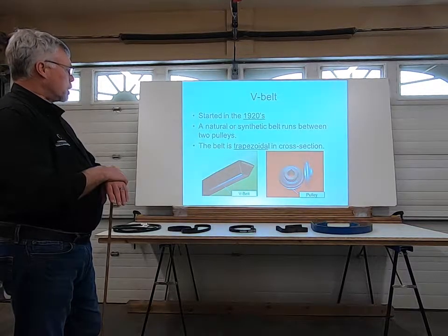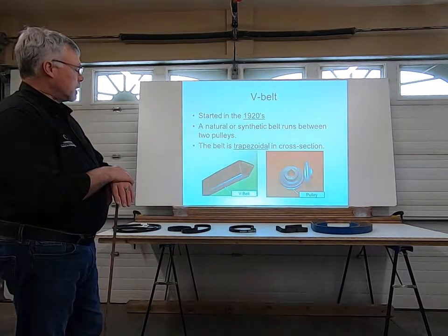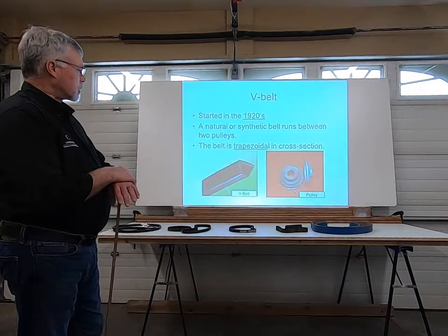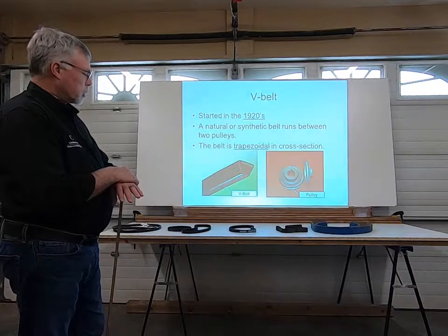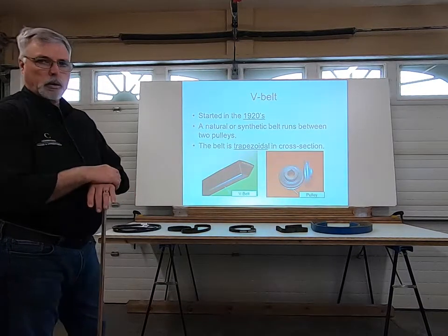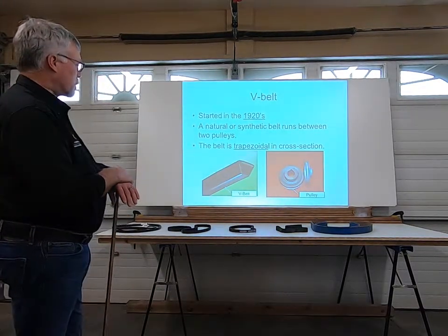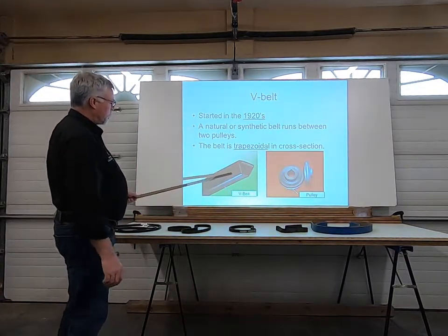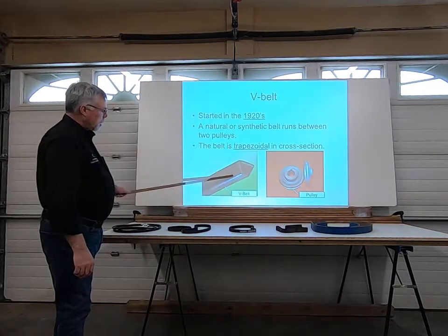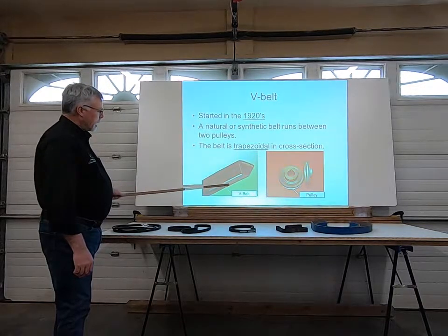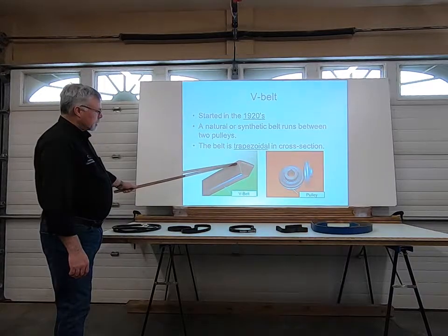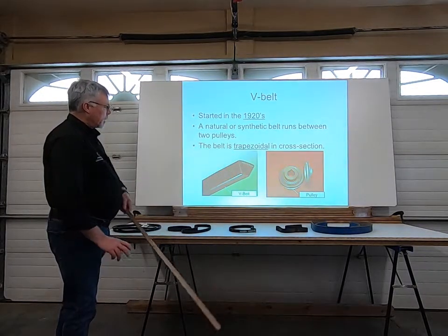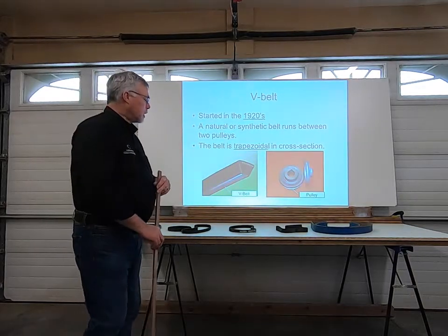So you have your motor that has your drive pulley, and then you have a shaft where that belt extends to, and what you're doing is you're trying to transfer the power from the motor to the shaft on the machine. Interesting, a lot of people think that when you're using a V belt that the contact is actually on the bottom side of the belt, when in fact the contact is on the side of the belt, and this is where belts can wear and get damaged if they're not aligned properly.